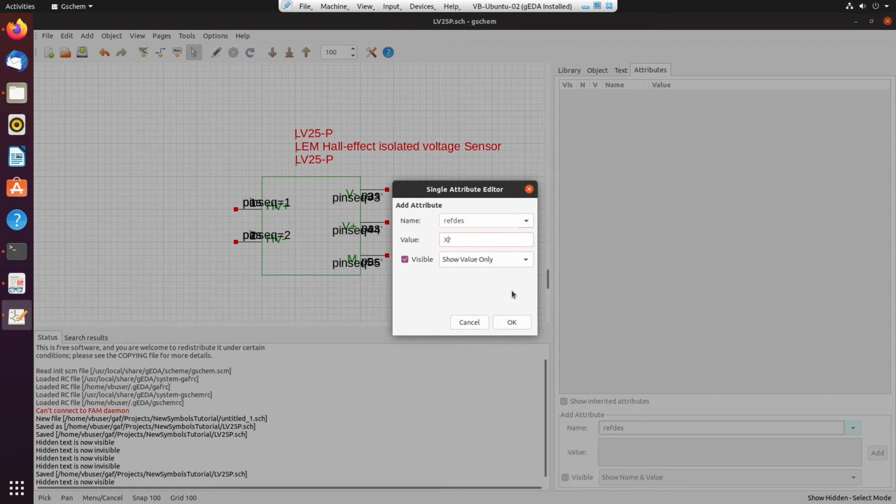So in practical terms, if you're going just from schematic to PCB, it really doesn't matter what these letters are. However, if you're going to SPICE simulation, then it does matter, because based on the reference designator, SPICE is going to interpret certain things. If your component is called R1, R2, R3, basically any reference designator starting with an R, then SPICE by default assumes that it's a resistor.